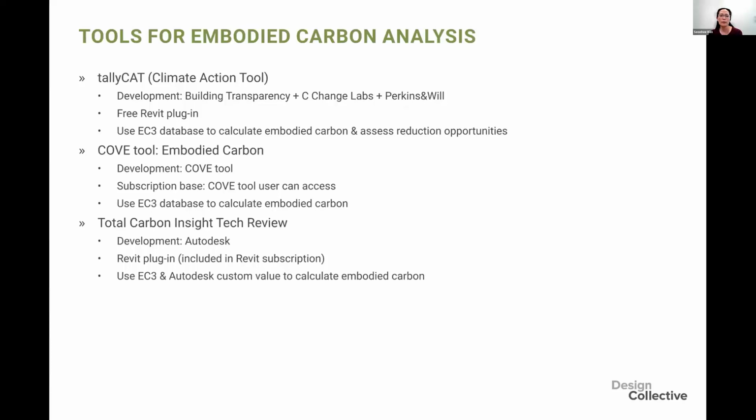TallyCAT is developed by Building Transparency, C Change Lab, and Perkins&Will, and it has a very similar method and way of approaching carbon as Tally. This is a free Revit plugin, and the link that I provided in the Mural, you can go and download the TallyCAT plugin. The actual meat of the database utilizes the EC3 database to calculate the embodied carbon and the carbon reduction opportunities.